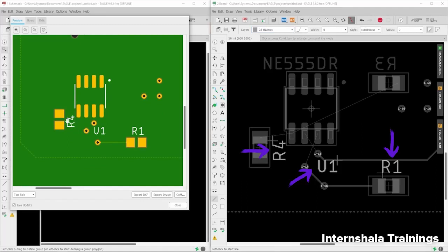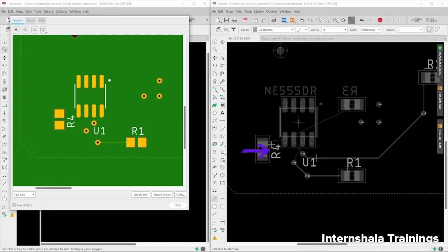And again, on a PCB it is called silk screen, but in the layout editor it is called the T names layer, or this text that you see is actually on the T names layer. So whenever you have to place the designators for a component, they should be on the T names layer. Okay, so I hope that it's clear now.